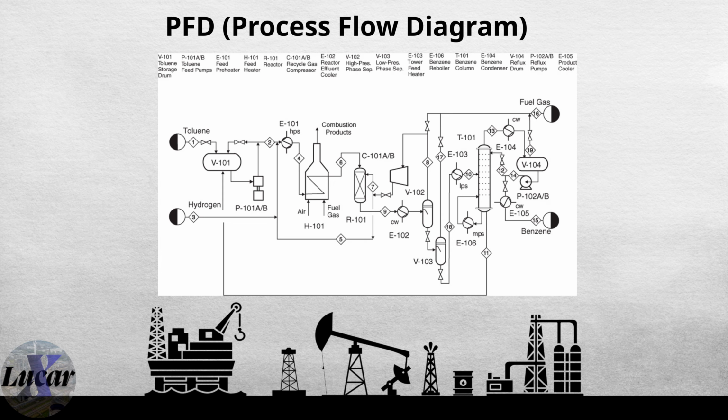In engineering terms, PFD includes major equipment symbols, pumps, heaters, main piping lines, flow directions, and basic data like temperatures, line number, or rates. It supports material and energy balances in basic design, but skips minor lines or instruments. In my upcoming videos, I'll be sharing the meanings of PFD symbols so that even complete beginners can read and